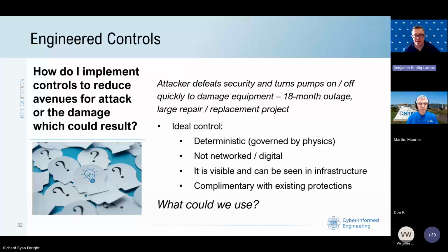And really it's the opportunity to center in on those and ask the questions: could I complement these, or replace them, or protect them with other mechanisms to reinforce some timing, reinforce a set point, reinforce some logical characteristics that I've programmed into the operation of this. And as you saw on the pump station, by focusing on that pump and asking those questions around the logic that's used to maintain that pump, we can recognize an opportunity, in this case, for a time delay relay, so that any command sent to us, we can hold it in for a set period of time.